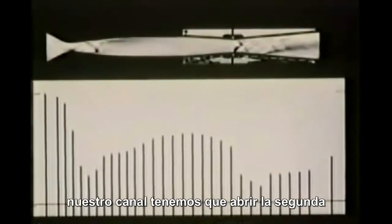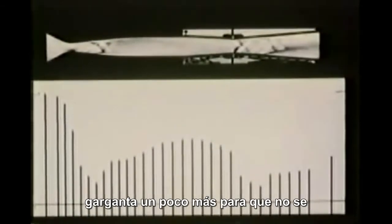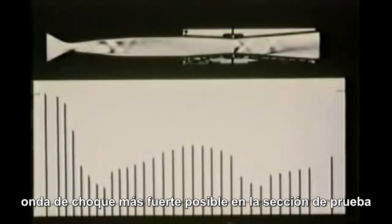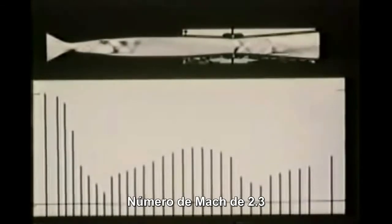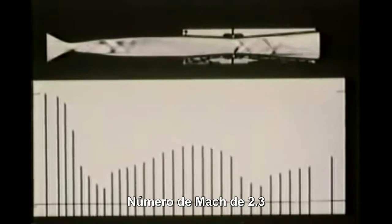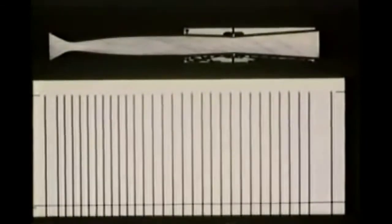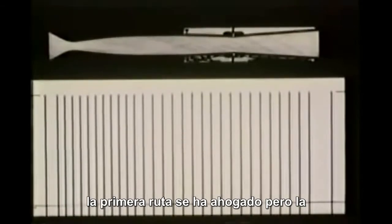To avoid blocking our channel, we have to open the second throat a little more so that it will not choke even for the strongest possible shock wave at the test section Mach number of 2.3. The first throat has choked, but the second has not. The back pressure is still decreasing, and the shock wave is moving downstream in the channel.